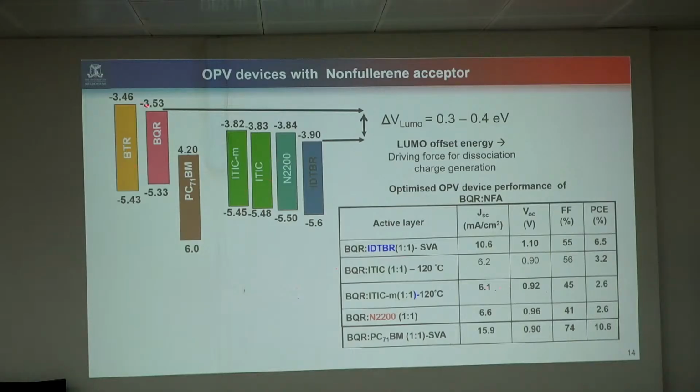So when you maintain the high offset energy, we have a very good short circuit current, and we have VOC and also you see fill factor. Fill factor means the squareness of this material is improving, and we get that. Even though this material has a capacity of more than 10% efficiency, because we are not maintaining enough offset, we are getting the loss of devices.